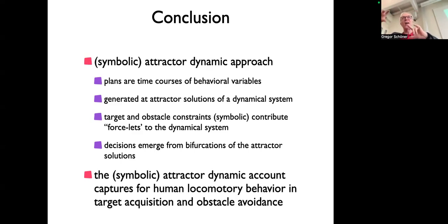And she developed a very ingenious way of how she added additional constraints like via points for the robots, and the follower versus the leader robot, and the follower has different dynamics to the leader robot for that to go around. And it's a quite elegant solution in that it's the sort of low-level stuff that we're talking about here. And it doesn't need any floor plan or a big time plan of the obstacles. When you do this classically, you would have a mathematical model of everything, and then you use one of those polygonal planners to do that, and it would not be easy to deal with that in real time. And if something shifts, you would have to replan and so on. So it's a much lower level kind of approach for that.